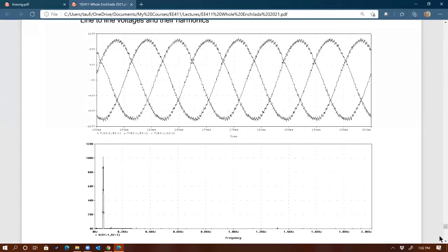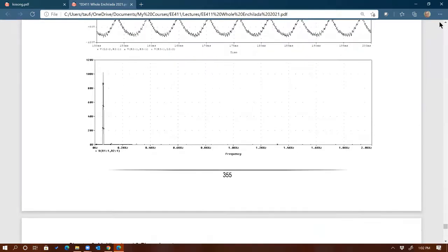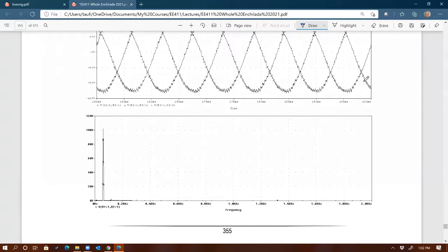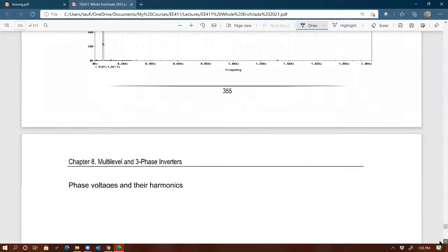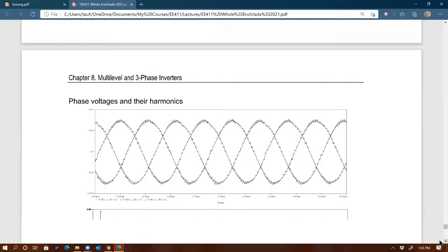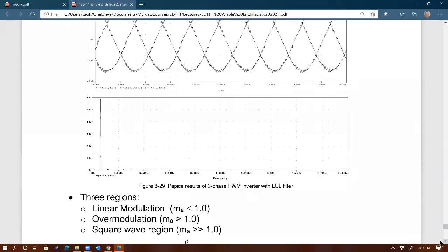Yes, that's the trade-off. The trade-off with that is that harmonics are further out, so it's easier for us to filter. Even though I didn't actually showcase it here, sorry. But keep in mind that harmonics are way out compared to the 60 hertz. But the disadvantage would be that you got more switching, right? More switching action, meaning you got more switching losses, right?